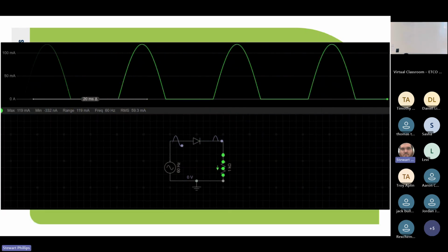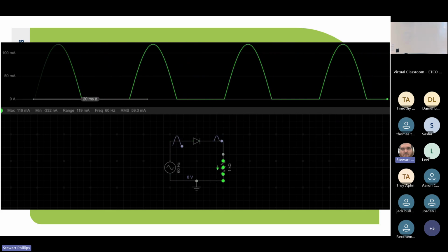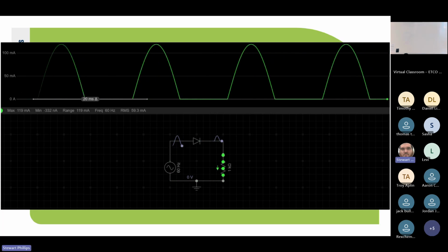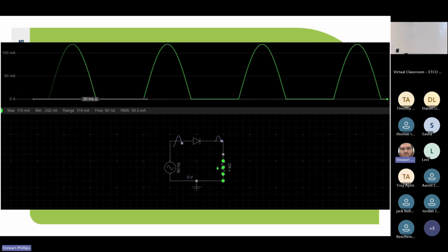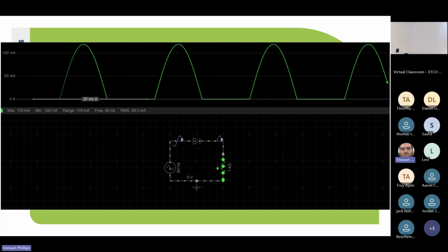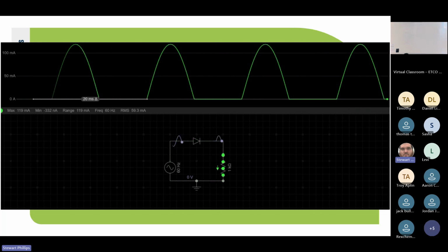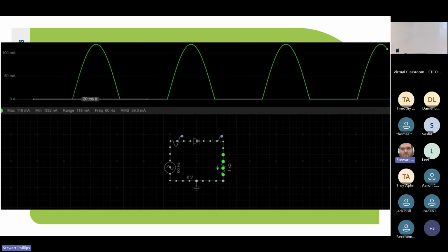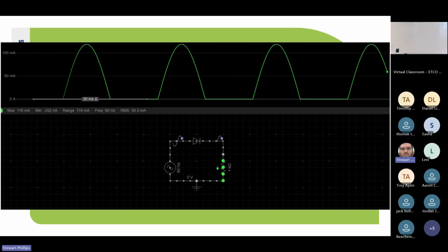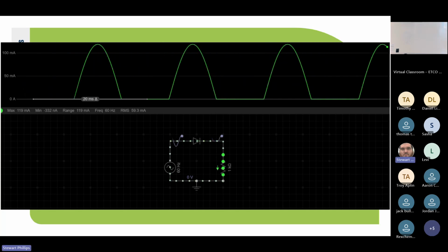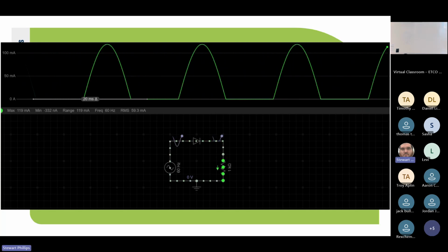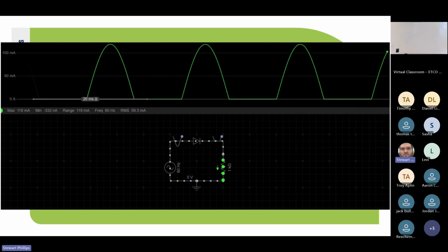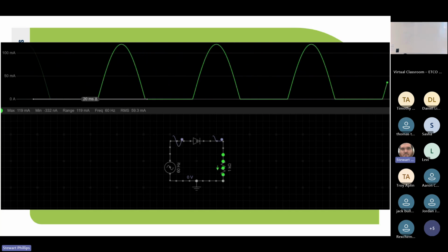it's probably coming through a bit glitchy on the live stream, but this is a half wave rectifier. If you look at the circuit, we only have one diode, so it's allowing current to flow in one direction. But when we get to the other half of the AC sine wave, it's basically being wasted. We've effectively thrown away half of the waveform. So it's what we call pulsating DC. Good enough for simple uses, but not very smooth. This might be okay for charging a battery, but it's not going to be good for anything like a computer.